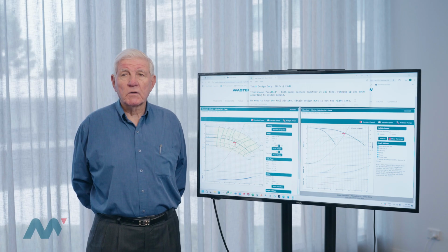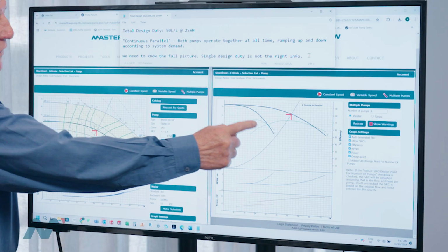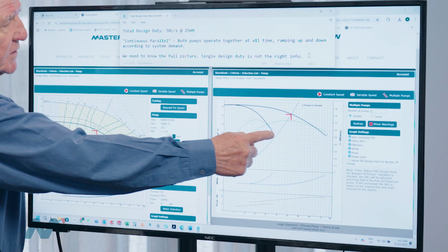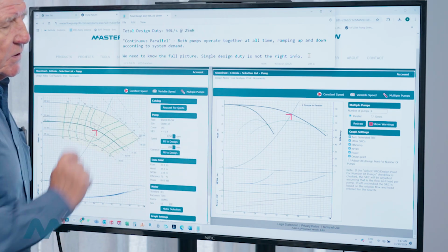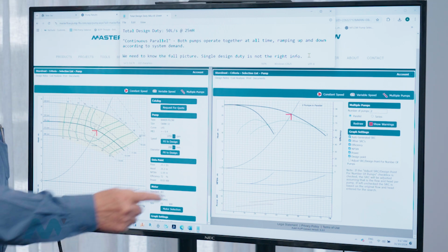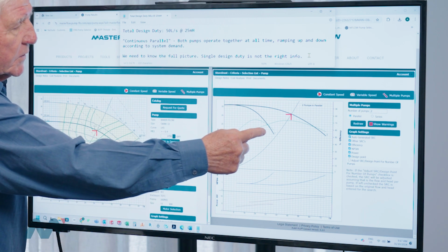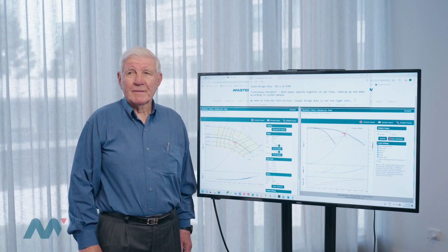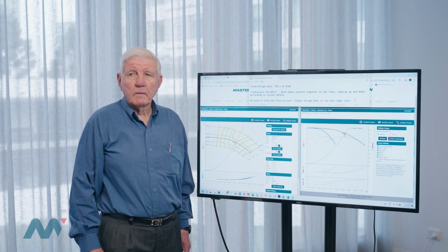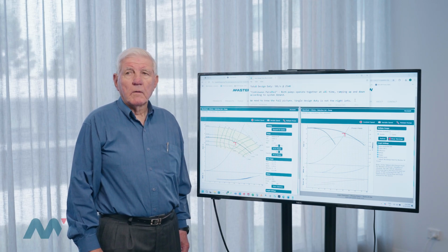And that means that they have to look at the intersection point of this single pump curve with the system resistance curve for two pumps operating in parallel. And if you look at that, you can see there is no intersection point. In that situation, the single pump will have the flow collapse at this point, and it will just drop down to an unknown, unstable position, and you'll get vibration, you'll get noise, you'll get all sorts of unpleasant phenomena. In order to bring the system curve back onto pump one, what we see is they manipulate the valves in the system.